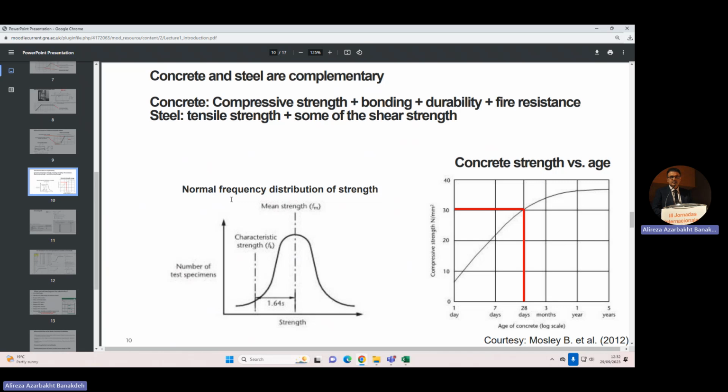From the day you pour the concrete, not when it's wet, but when it's a little bit dry, you should pour a little bit of water around the top of it just to make it wet, humid. Otherwise, it will get dry soon. It needs water to be mature. So that's why you shouldn't add anything extra beyond what is advised. It can make the process worse than you think. But don't load your structure before 28 days.